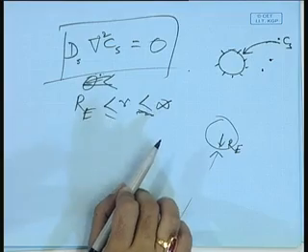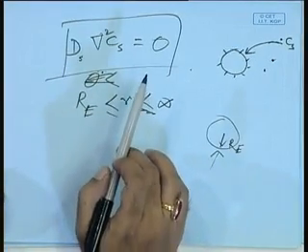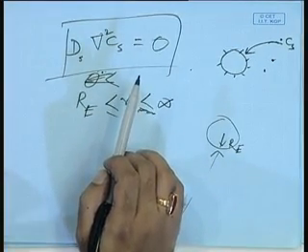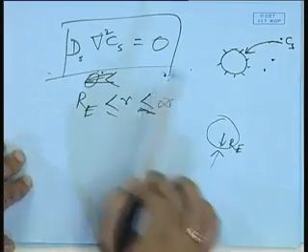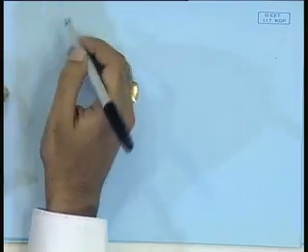All reactions are happening on the surface of the matrix, as I tried to specify before. Is that clear to everybody? So all reactions are happening on the surface, and when I am writing my equation in the domain of interest, there is no reaction. Yes, we will include the reaction in the boundary condition. I'll come to that, but I'm going a little slow.